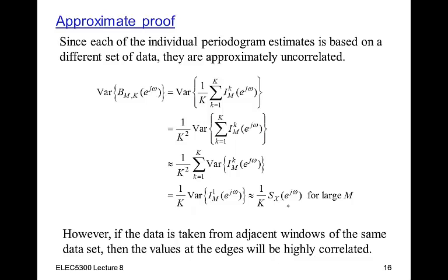the power spectral density, which is a constant, and so this thing, as k goes to infinity, will go to 0. This is kind of an overly optimistic estimate because, in fact, these windows here won't be uncorrelated. In particular, the values at the edges will typically be highly correlated, depending on how quickly the random process changes. But anyways, that's a rough idea of what's happening here.